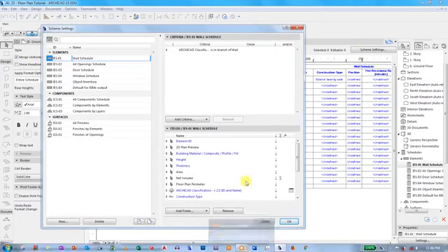So let's wait for it to load. When that loads, I'll be saving it as a wall schedule. That is my file name. And down here under save as type, I'll click on this drop down, then I'll select Excel workbook, which is an Excel file. Then I want this Excel file to open after I have saved it, so I'll choose this button, open file after save. Then I'll click save. What that does is it saves the file, and also Excel will start opening. So I will have the file open in Excel.